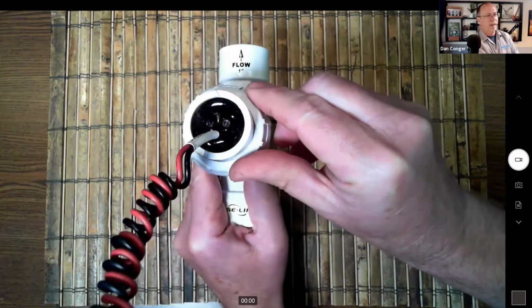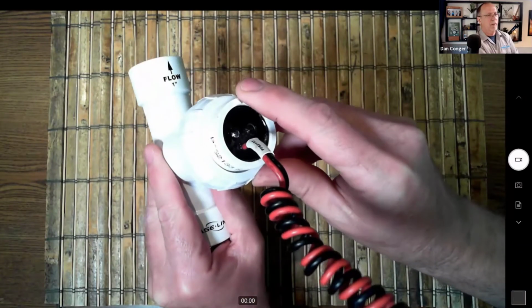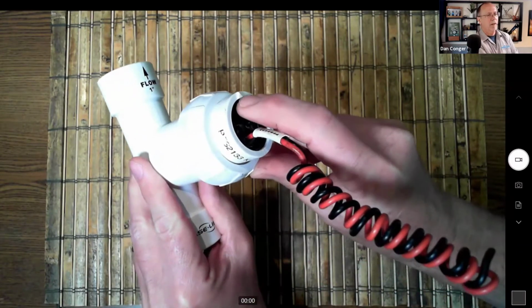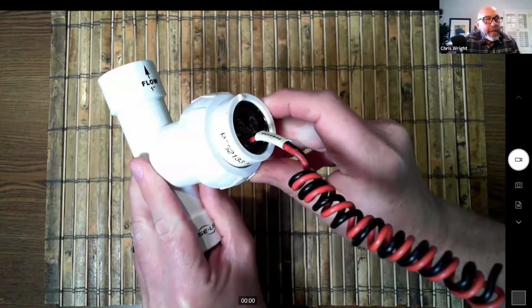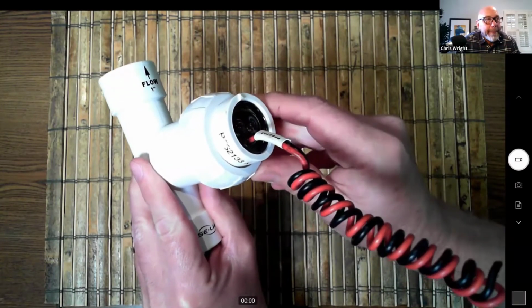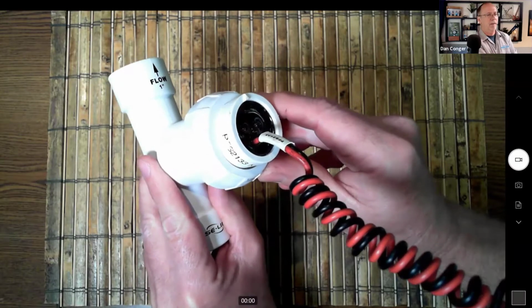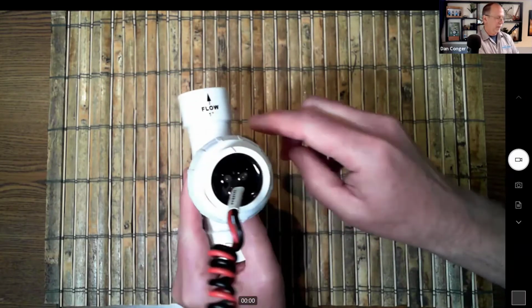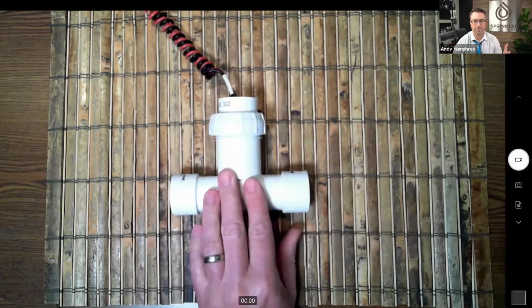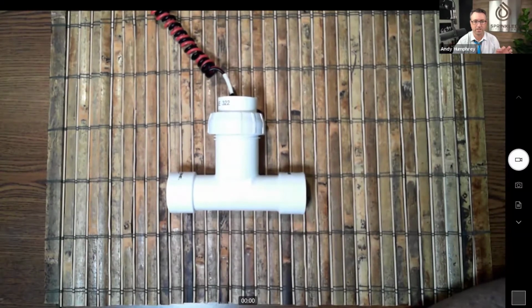There's a little arrow, right? It doesn't show up quite in the light. There's this little arrow indicating the flow too. So that's built in as well. So there's a clue to look for. That's going to line up with the flow. Yep. And then when water's flowing through that and it's connected to the controller, the lights should flash. So that's the visual test that there's water running through there.